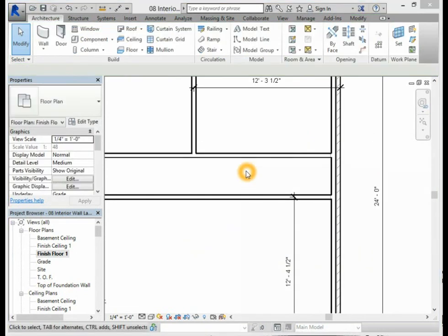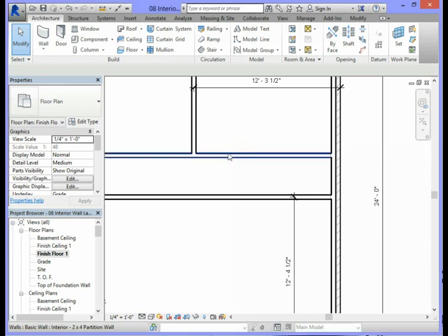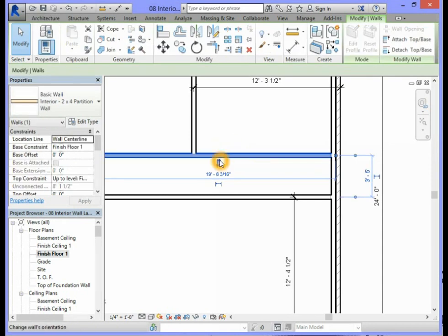To lock the two interior walls that lay out the hallway, you will need to select one of the interior walls. You will select the witness line for the temporary dimension until it references the center of the two walls.